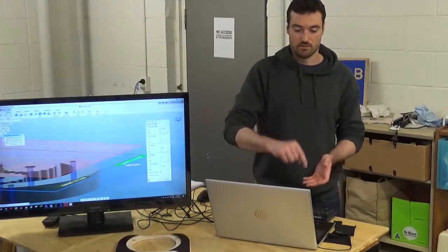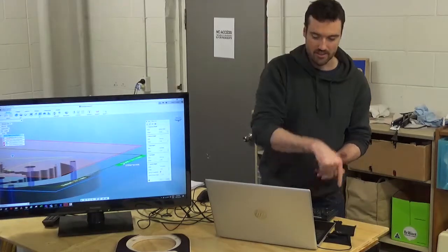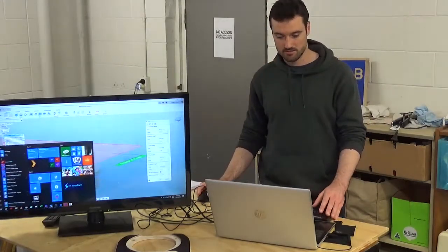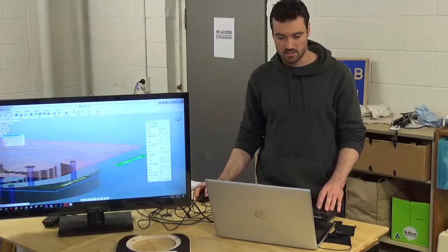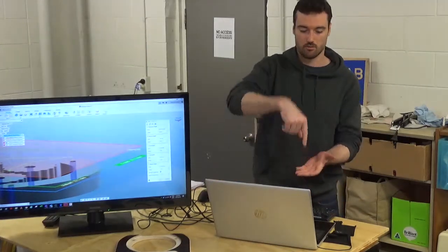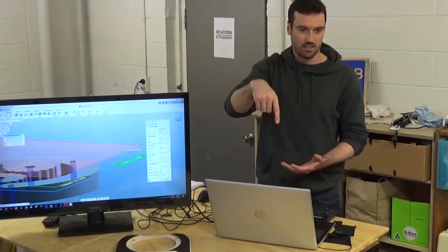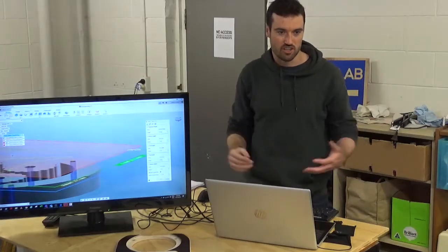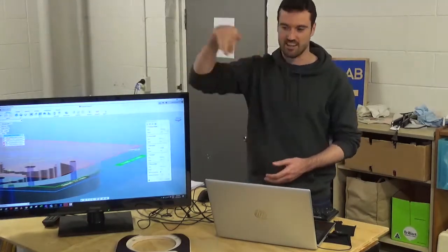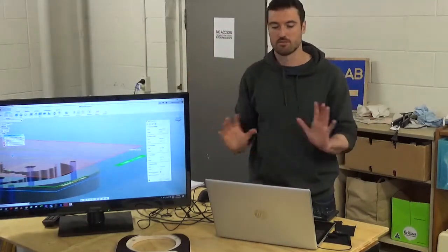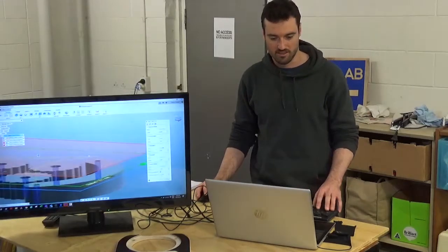So basically what this will do is retract above the board and then plunge back in. And this is the clearance layer. Before it moves to the next operation, it'll go to that height. So it's really safe, away from any clamps or anything you're using to hold down the piece. Okay?